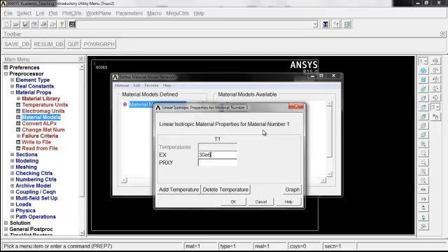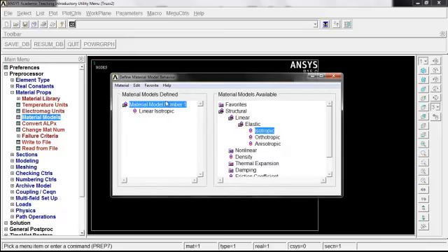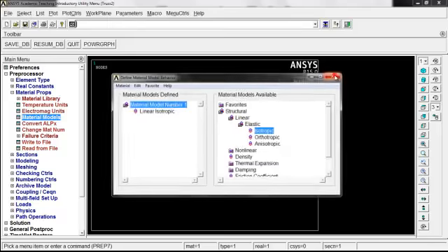And this is pounds per inch squared. So we're already in inches, so that's good. We're staying there. We're doing pounds now for our force. Right, so we're going to remember that. We can plug in here for the Poisson's ratio. We'll put in there 0.3. And go ahead and click on OK. And we can go ahead and just close this window for the material behavior.